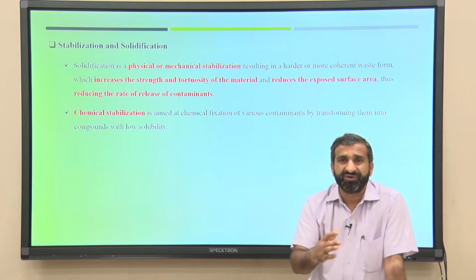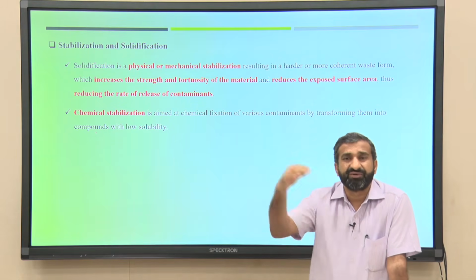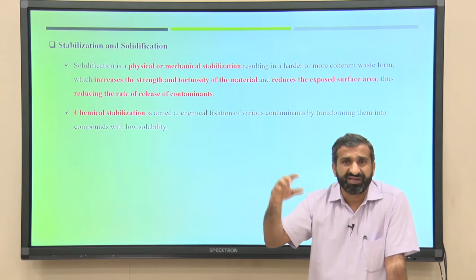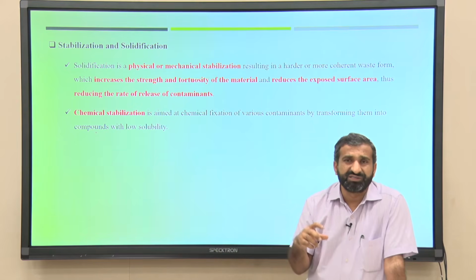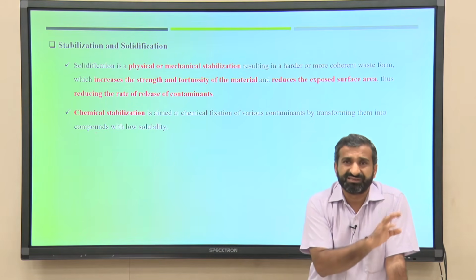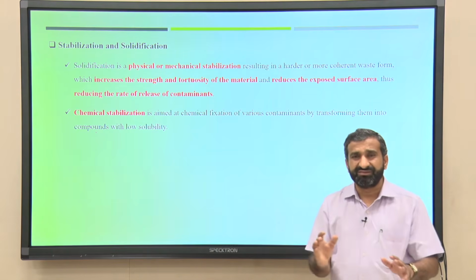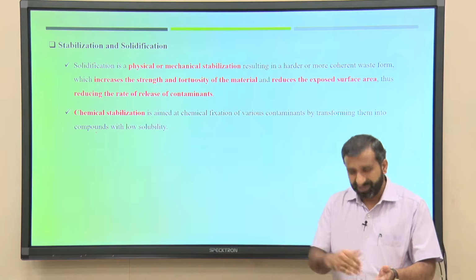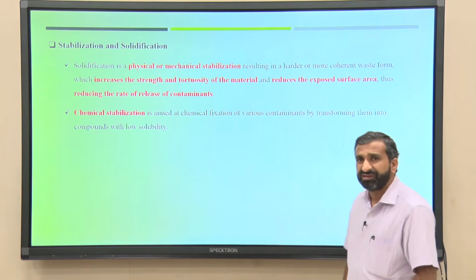If you maintain a higher pH of this bottom ash, like about 7, 8 or 9 pH of this particular solid residue, it is very difficult for these metals to get leached out at this higher pH. So, that is also one of the ways we can reduce the solubility of these metals from the solid residue.